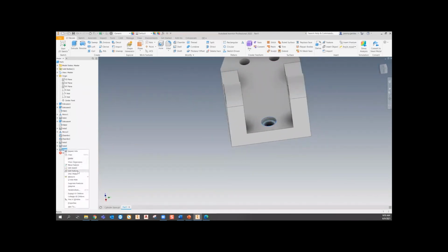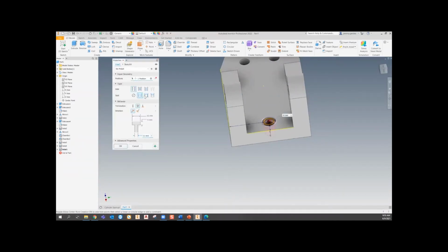And say, you know, well, we're going to change the fastener to a different diameter of a head. We can easily change that instead of going back into a sketch if we would have done that as a sketch command. So that's the benefit of using the hole commands for sketches for creating holes.